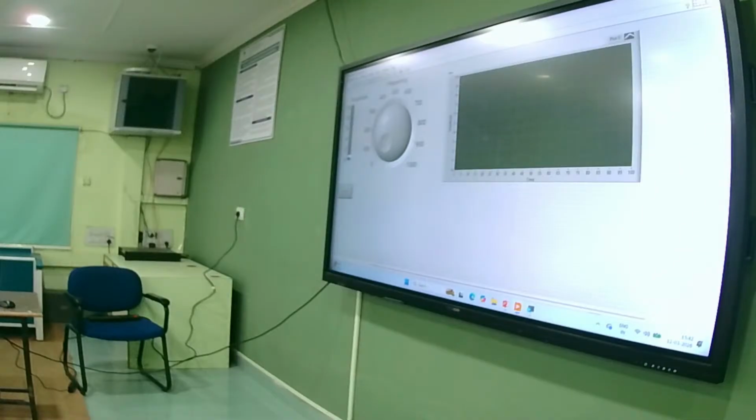The second and most dangerous part is your amplitude. If you keep an amplitude of 10, literally 10 volts will come out of your PC. You should not keep 10 volts out of your PC because its speakers are very feeble. So keep the maximum amplitude as 2.